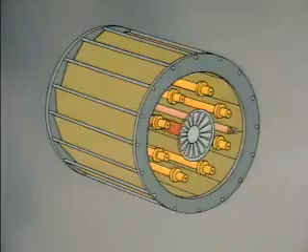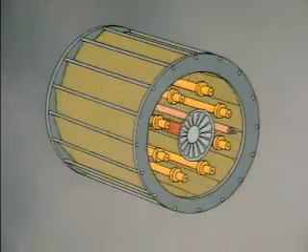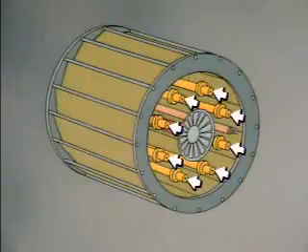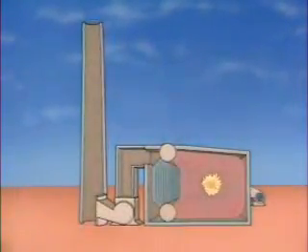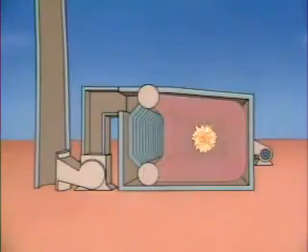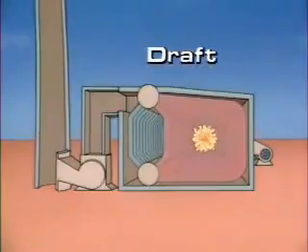This burner, for example, is a typical gas burner. It uses dampers or registers to regulate the amount of air entering the burner. Pipes called spuds inject natural gas into the boiler. The airflow into a boiler provides oxygen for combustion. Gases produced during combustion flow out of the boiler and are discharged from the stack. The flow of air and other gases through a boiler is referred to as draft.